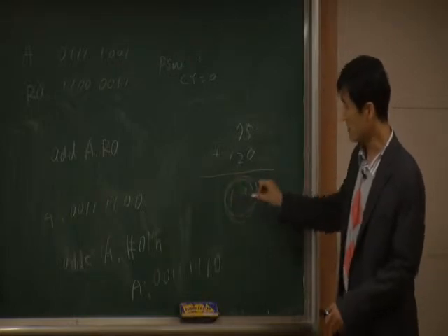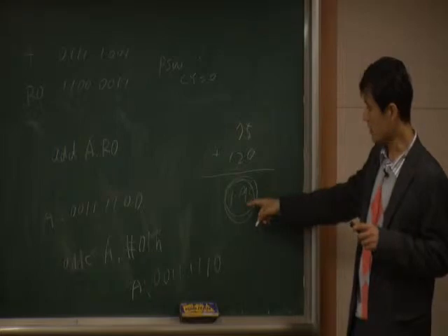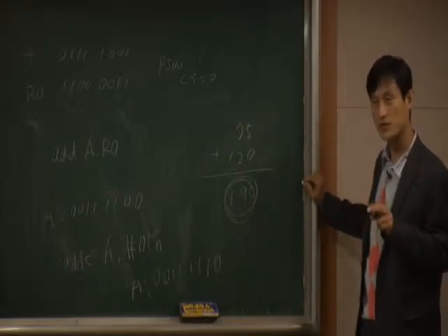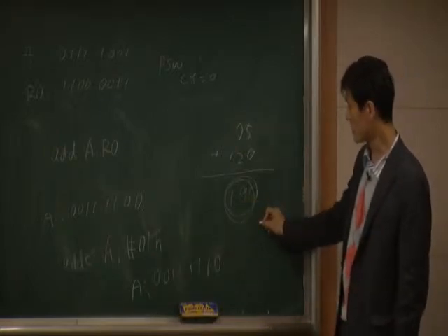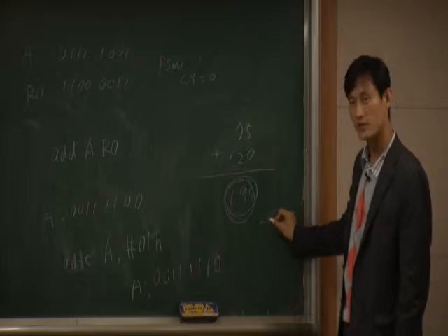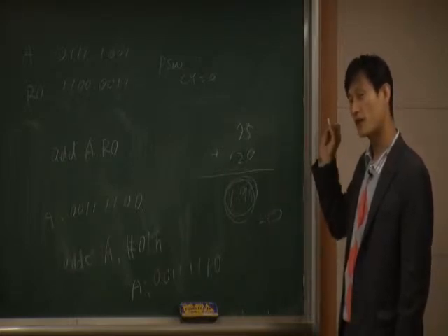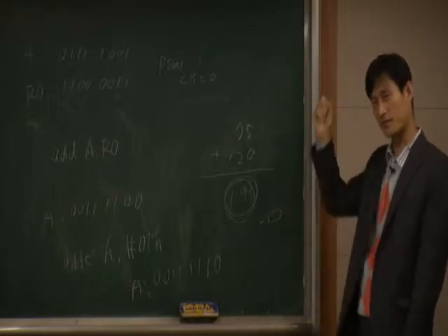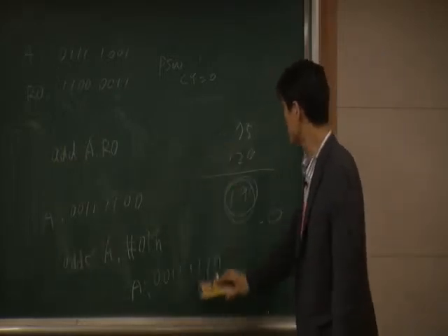But in our case, if you use 2's complement, then simply this value becomes too big. Right? If you use 2's complement. So therefore, this value now becomes minus some value. And then what flag do you have? In this case, overflow. Yeah, you have the overflow flag up.